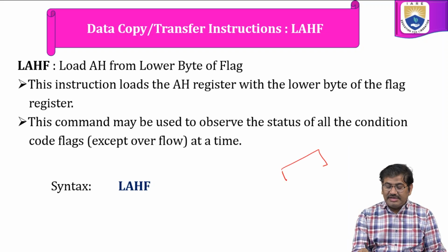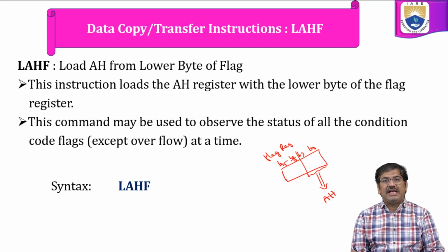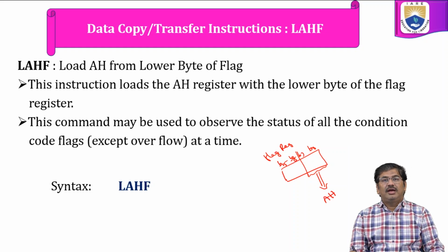As we know, the flag register is 16-bit size, that is bit 0 to bit 7 and bit 8 to bit 15. This is what the flag register contains. So whatever the contents are there in the lower byte, that is from B0 to B7, these contents are transferred into the AH register, as the AH register is an 8-bit register.